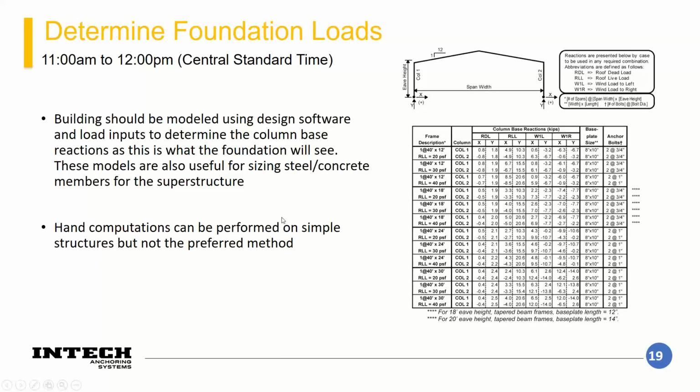So once you've determined what your governing design case is, you really want to model the entire structure. And the desired outcome of modeling your structure like this is you want to understand what the column reactions are at the base. Because how these columns are imparting the load on the base is essentially the load that the piles are going to see as well.